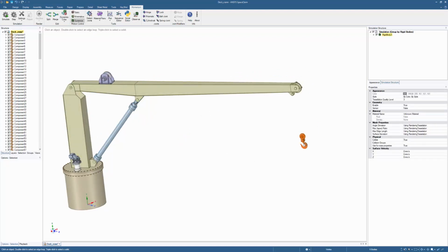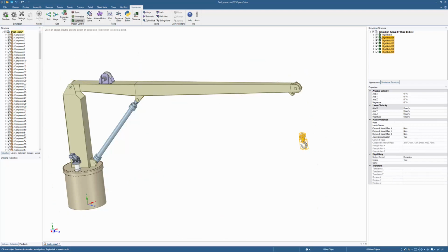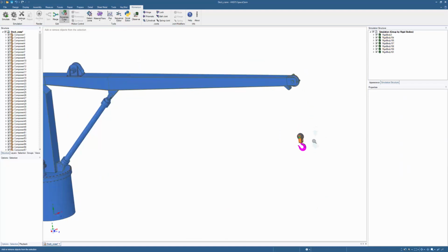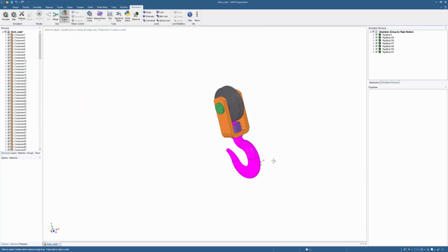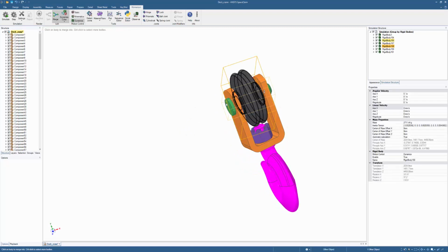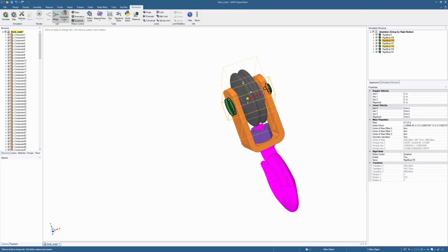So we start by selecting this crane hook and just split that. Then we'll get a number of separate rigid bodies. Now we have to find out which are supposed to belong to each other. We see that we have a sheave construction, this circular object, and that should belong to the green axis that goes through the system. So we will merge those two.